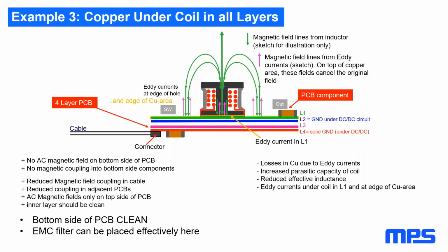But if you have a 2-layer winding on the core, the parasitic capacitance from start of winding to the environment is much lower than from the end of winding. And that's the point that is important. So it's about the E-field radiation, which means it's a capacitive coupling. Capacitive coupling from the switch node, high dV/dt, to the environment is the topic. I hope this is explaining it.